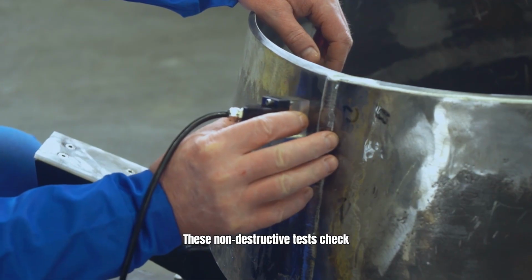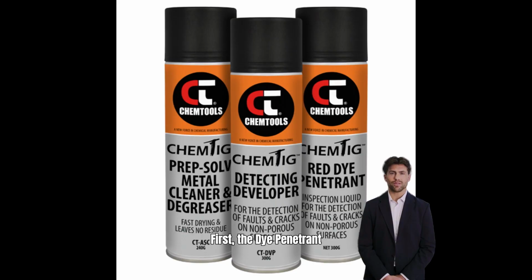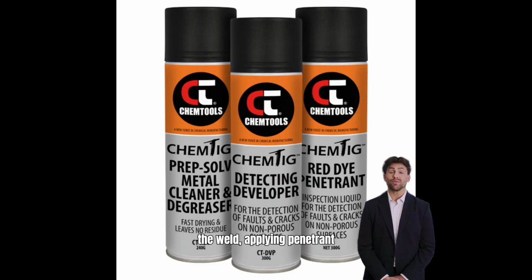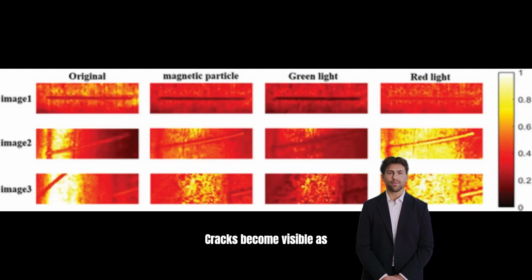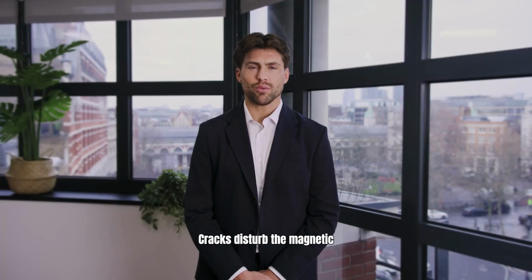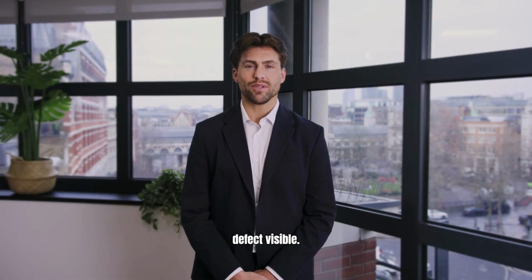These non-destructive tests check internal and surface defects without damaging the weld. First, the dye penetrant test, or DPT, is used for surface cracks. The process involves cleaning the weld, applying penetrant liquid, letting it seep, removing excess, and then applying developer powder. Cracks become visible as red lines. Next, the magnetic particle test, or MPT, is only for ferromagnetic materials like carbon steel. Cracks disturb the magnetic field, causing iron particles to gather, making the defect visible.